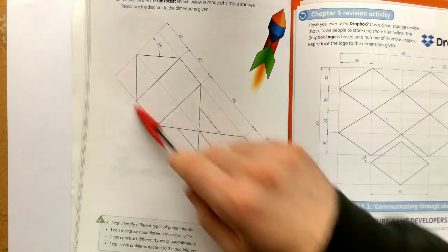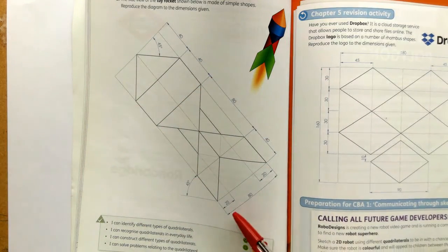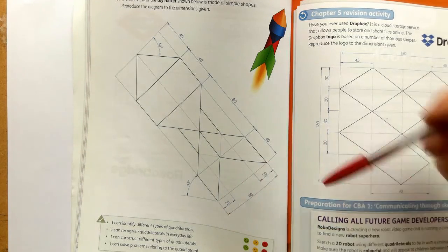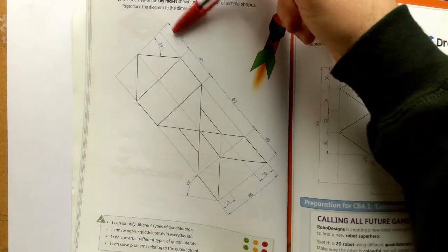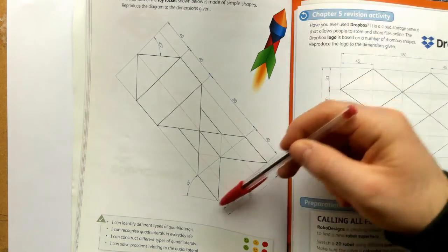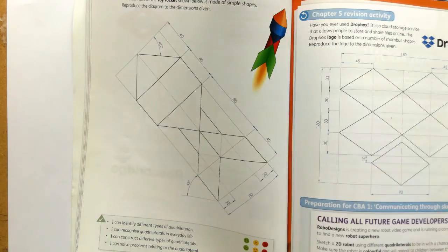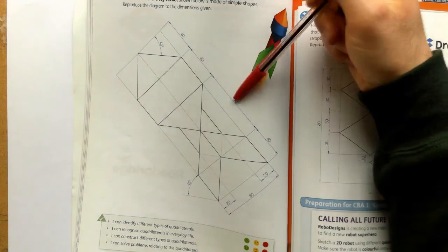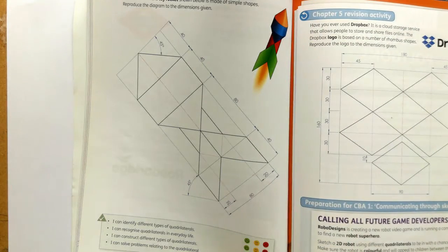I'm going to draw in that rectangle for it all to fit inside, and I know that rectangle is 80 millimeters long going this way, and then if I add up this, it's 80 plus 80, 160, it's actually 200 long, so it's 80 here and then 200 long here. Okay, and then what I'll do is I'll put in my various measurements of 40, 40, 80, 40, and then the 20s and so on to be able to complete it.